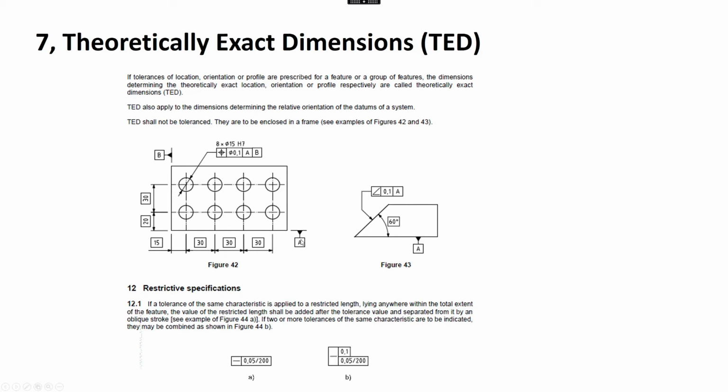In this particular case, normally the top face would be datum A, and then this would be B, and then this would be C. And we'll go into why in a minute and exactly what this means.